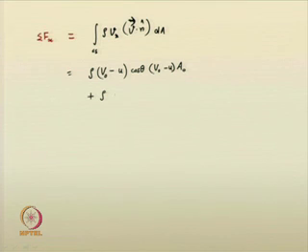Plus, at the inlet, we are talking about the net momentum outflux, right. So, V 0 minus u into V 0 minus u into A 0 into minus 1 we have to give. Why? Because at the inlet, V dot n will be a negative quantity, isn't it? So, therefore, we are giving it into minus 1. So, you can say this is nothing but equal to the force exerted by the fluid.